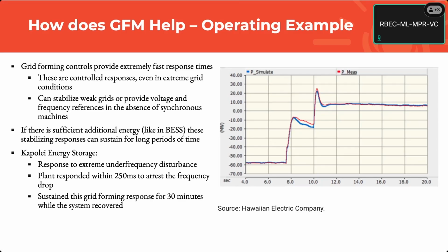There should be a corresponding plot of frequency here. I can probably find it if you want, but basically the frequency is falling extremely quickly, and proportionate to that, you can think of the angle in the system. If the frequency is crashing, the angle is moving, right? And this is just the uncontrolled response to that angle moving. So you get active power shooting up immediately like this. There's no delay, there's no PI controller, there's no controls actually acting in here. It's just doing nothing inside, and it goes up and then it comes back down.